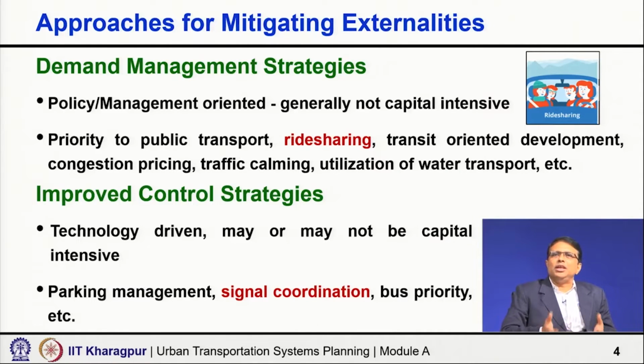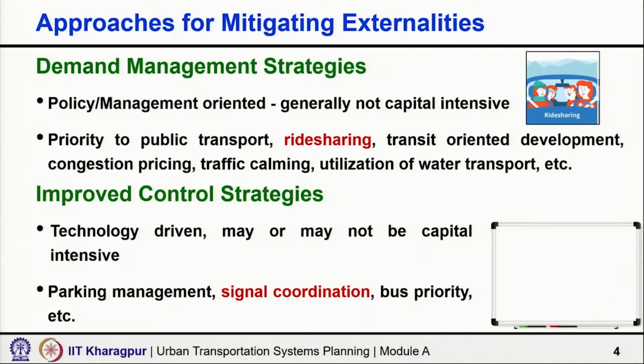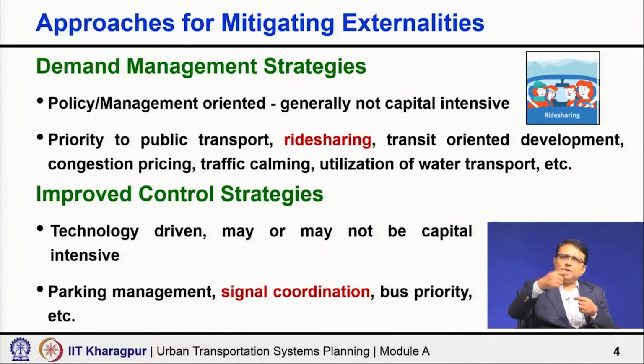at an intersection, obviously the delay will decrease, and the traffic can use it in a better way. Similarly, if I can coordinate the signal systems, you have 2 or 3 signals, right. So many times you find the signal actually becomes red by the time you reach near the signal. When you are away from the signal, you find green, there is no vehicle in front of the signal, but by the time you reach in front of the signal, it becomes red. So it could be reversed, right. When the vehicle bunch or platoon of vehicles is away from the signal, it is red, but by the time the platoon reaches the signal, it becomes green. So how do I coordinate this green time, so that once a vehicle gets green, all subsequent signals are coordinated and it starts getting green in all the signals, right.